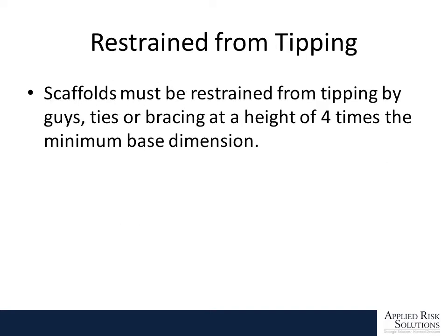You've got to restrain scaffolding from tipping. Basically, once you get 4 times higher than the width, you've got to tie it into the building. For example, if your scaffolding is 4 feet wide, when you get to a height of 16 feet, you've got to tie it in.